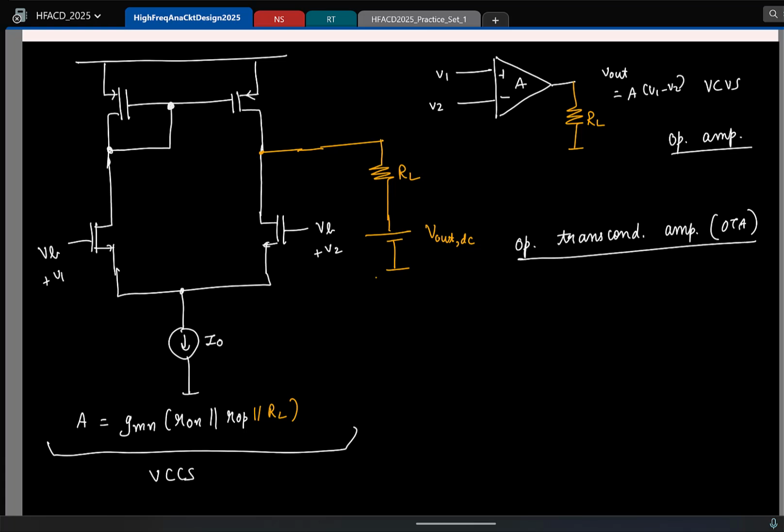Yeah, so we have an OTA, and the symbol for the OTA is a quadrilateral instead of a triangle now. So this is V1, V2. So just like how here the output voltage was fixed in a VCVS, in a VCCS, what is fixed, do you think? Output current will be fixed. Okay. And this will be equal to a proportionality constant gm times (V1 minus V2). And you have its own intrinsic R out, like this.